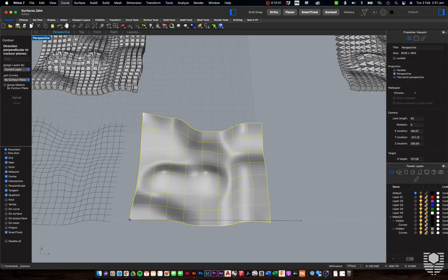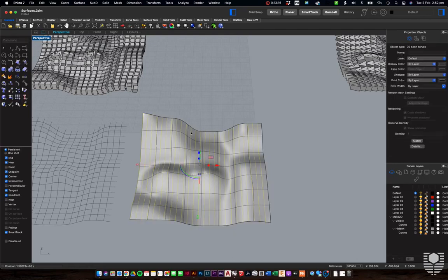So I'm going to draw a perpendicular plane again, make sure our ortho is turned on. I click here, it's going to start cutting some vertical lines this way, the opposite direction in whatever way this line's going in. So if I go this way, it's going to go up the surface. Now I need to say at what regular distance do I want. I'm going to go ahead with 4 millimeters for this one, and I click enter, and there we have it.